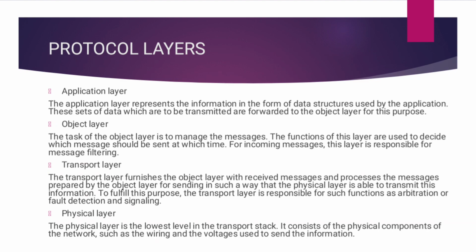And the second one is the object layer. The task of the object layer is to manage the messages. The functions of the layer are used to decide which messages should be sent at which time. For incoming messages, this layer is responsible for message filtering.